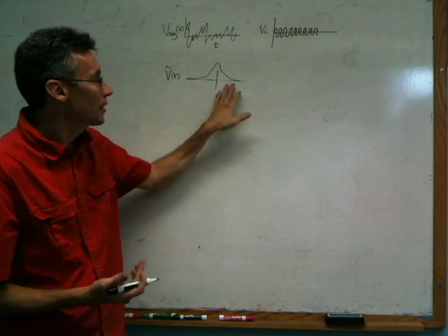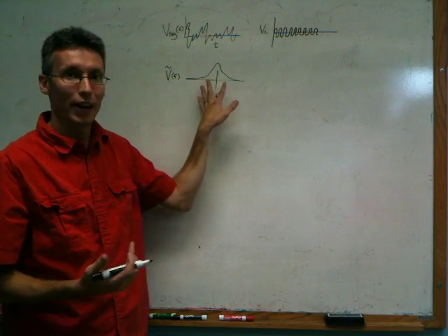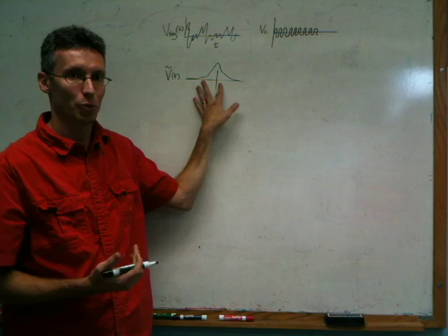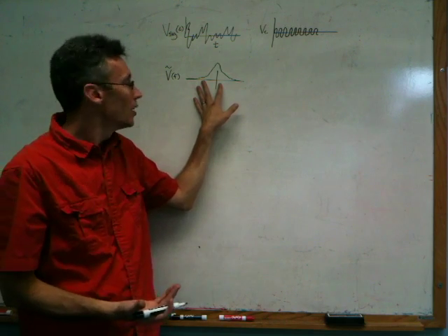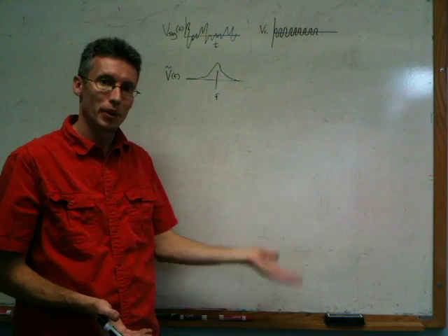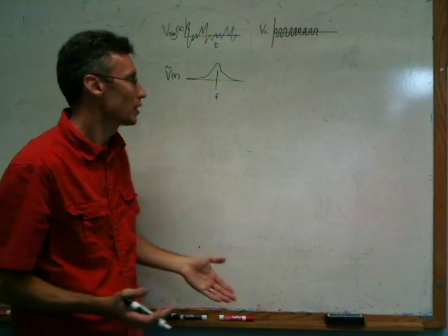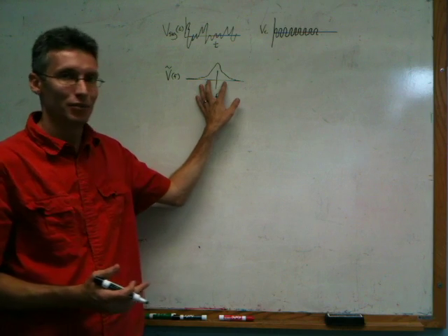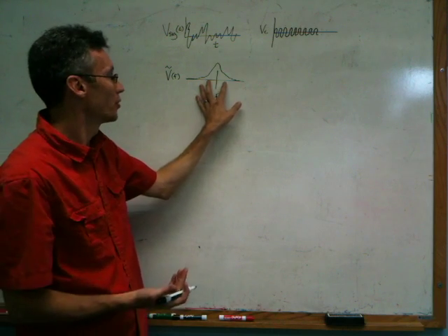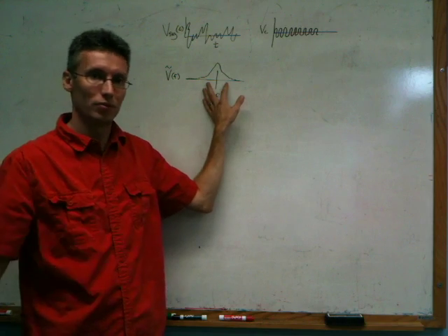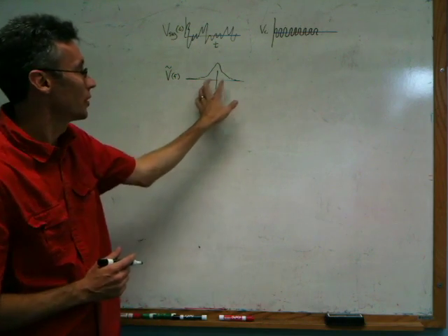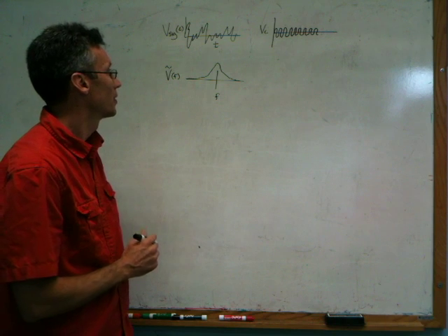And depending on the type of signal, we'll get different characteristic shapes for this signal spectrum. If it's an audio signal, we expect most of the information to be between 20 hertz and 20 kilohertz. And in practice, most radio transmissions or audio transmissions don't transmit up to 20 kilohertz, but limit the bandwidth somewhat below that.